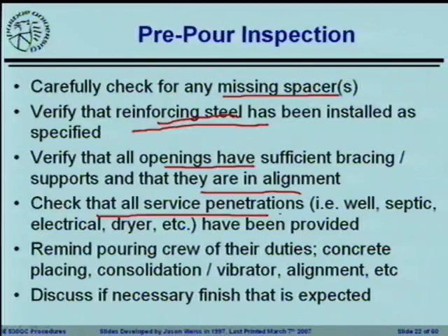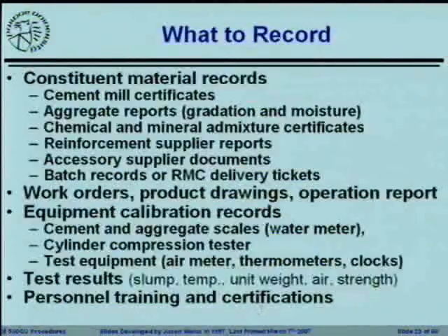All right, during the construction, you want to make sure you remind the crew of all of their duties. All right, during the concrete placing operation, where they're placing the concrete, who is vibrating. All right, you don't want all of a sudden when the concrete shows up, nobody thinks that they're running the wheelbarrow. All right, you want everyone to know what it is that they're doing, and you want to make sure that you discuss what you're expecting in terms of the concrete finish. Is it going to be a broom finish, hard trowel finish? You want to make sure that everybody's aware of it before it starts to show up.